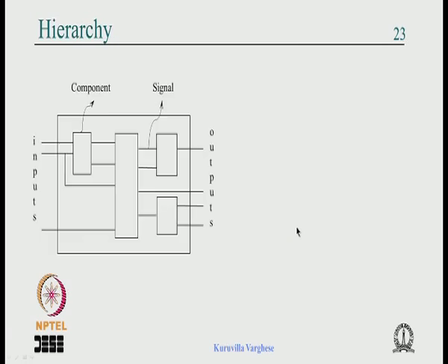So let us go ahead and come to today's part, and here we see a model of description called the structural model of the VHDL code, which enables us to do the hierarchical design or the top down design. And we have seen already how we have designed the CPU top down. We put a black box CPU, say level 1, where it was an interconnection of various components. So we will see how that can be done in VHDL using the structural code. That is the basic idea.